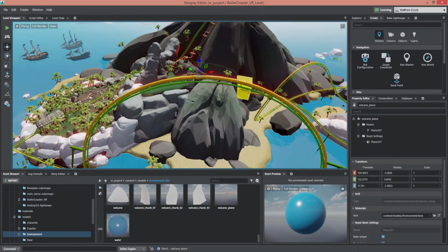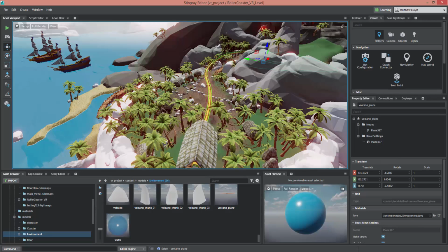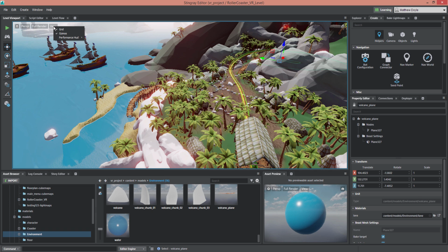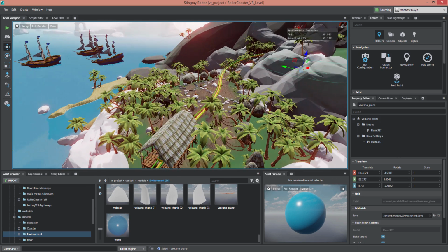So we talked about the importance of VSync and maintaining a good frame rate. And one way that you can determine what kind of frame rate you're going to be getting is using the performance visualizing tools inside of Stingray here. So if we go to the viewport, click on view here, we have the performance HUD, and we can turn on FPS here. And this tells us what our FPS is inside the viewport. And in this case, we're pretty much hitting 60 frames a second. Now bear in mind the viewport is locked to 60 frames a second maximum. So even if you're getting more than 60 frames a second, you're not going to see that number go up any higher. Whereas when Stingray pipes out the images to the Oculus, they're going to be locked, in the case of DevKit 2, to 75 hertz, and the consumer version would be 90 hertz or 90 frames per second.